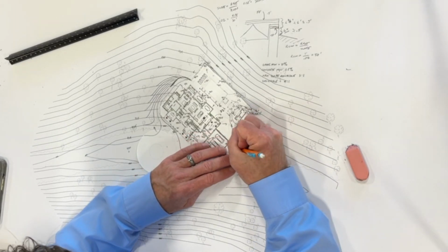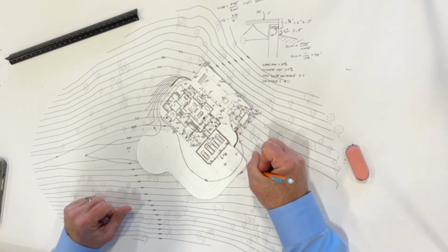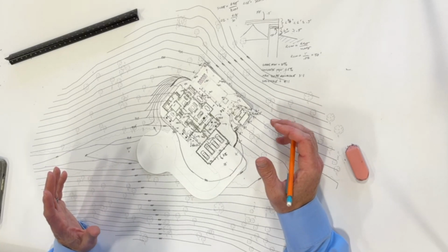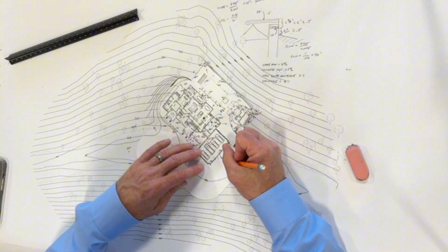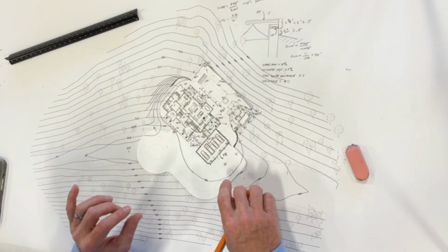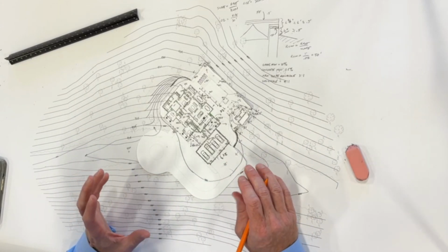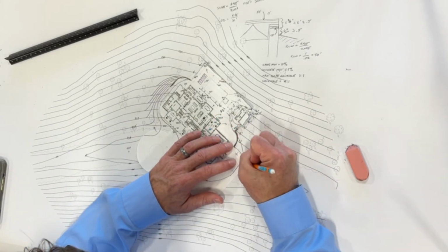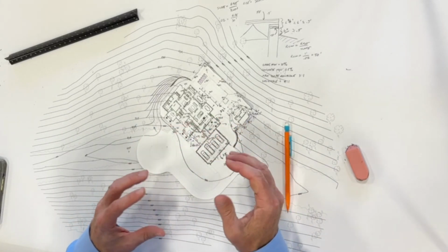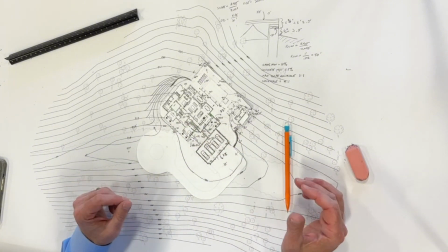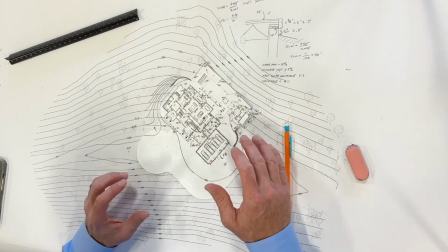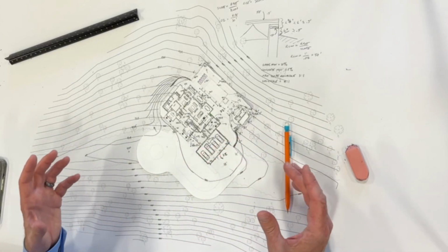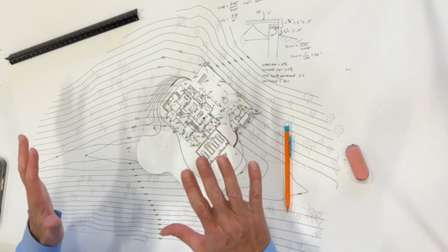And then actually what this means is this retaining wall needs to come around the driveway, right? So as we're looking at this, we may go, okay, we want to maybe do something different because we're going to be building some big retaining walls. So now, it does tell me I don't want the driveway that flat because we're fighting this giant retaining wall over here, which is still 4 foot right here. So if we steepen up the driveway to lessen the retaining wall, but I don't know, maybe what it does is it just makes the retaining wall 1 foot lower, but then you got a steeper driveway. If I were them, I'd probably still want the flatter driveway and just have 1 foot high retaining wall. So you got to kind of think about that.